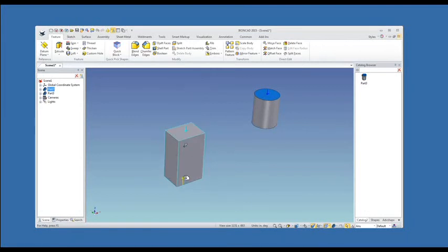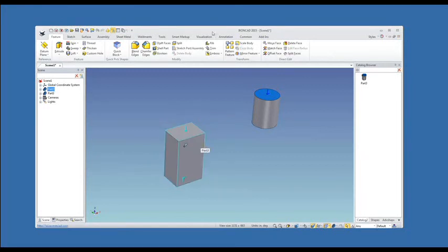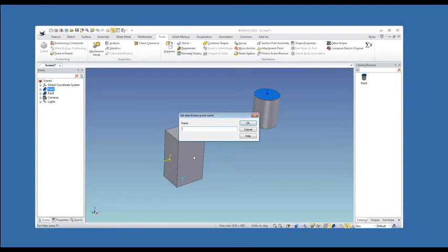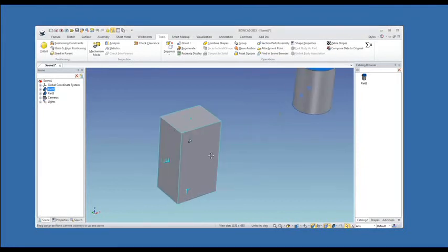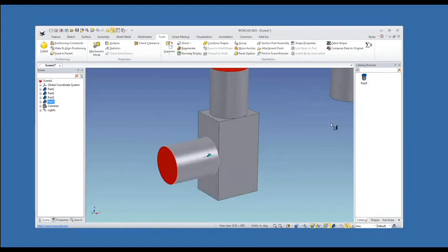And even if you had 2 neutrals, like I'll go back to 2 neutrals, this is another point that is good to bring up. And actually maybe I'll even make a third, because you can have as many attachment points on a part as you want. And then I'll put one here, and I'll also call that 1_m. Now the question is, when I drag out, which one does it snap to? Well, if you left click and drag, it'll just get whatever you're closest to. So if I come in and get near, it's going to grab the one that's closest.